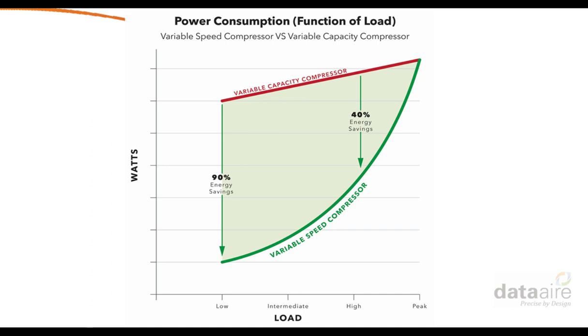What happens though is the evaporator temperature will rise and the condensing temperature will fall, reducing the compressor lift required and increasing the efficiency. So that's effectively what's happening, in addition to the motor spinning much slower. So that's why you're getting such energy savings like that.